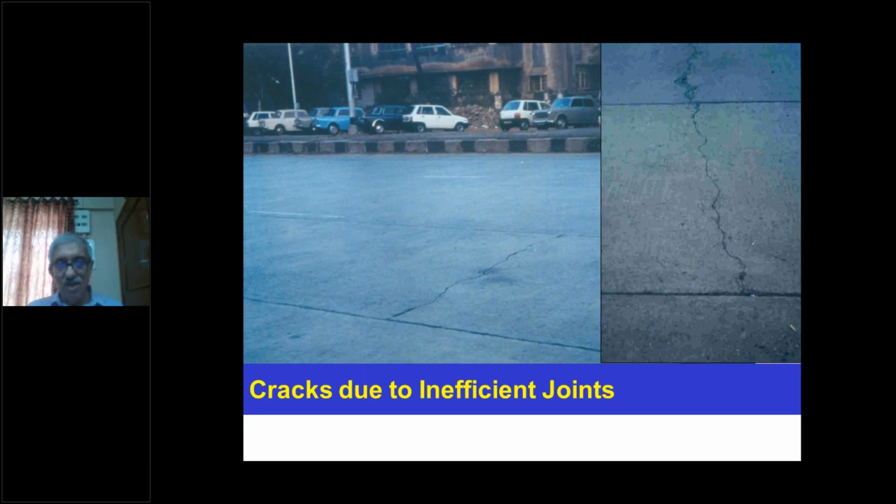Concrete shrinks equally in all directions. Please make a note of that. So you can't have a rectangular groove pattern. For example, this length is long here, this length is short, so the concrete cracked in between. Here you can see a close-up view all along where the length was more, the concrete cracked in between due to grooving of the concrete or joints in the concrete.